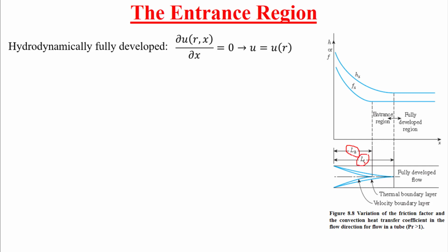Which one is larger, L H or L thermal? In order to answer this question, we need to ask ourselves whether we are in the laminar region or we have turbulent flow, because this question is very essential.